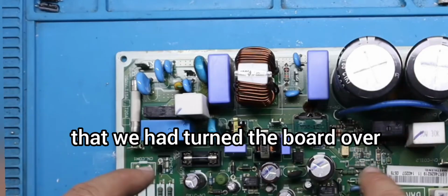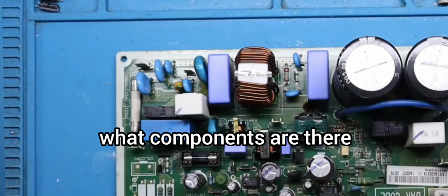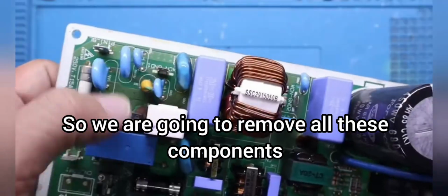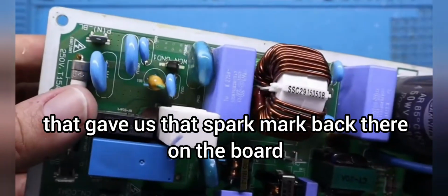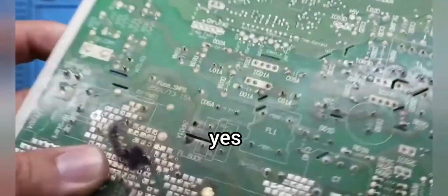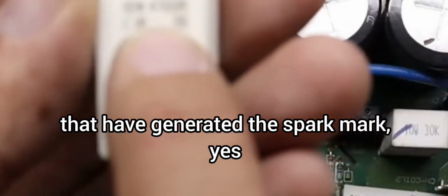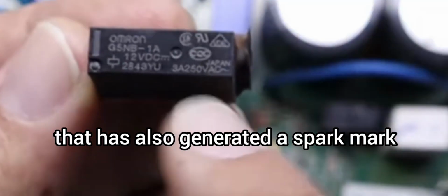Because the spark mark that we saw when we turned the board over was in this area. So we have to see what components are there that have failed. So we are going to remove all these components that are here and we are going to see what is the error that gave us that spark mark back there on the board. So it must be verified very carefully. Here we have two components that have generated the spark mark. Yes, this is a resistor, apparently of 470 ohms. And this other component has also generated a spark mark and has melted.